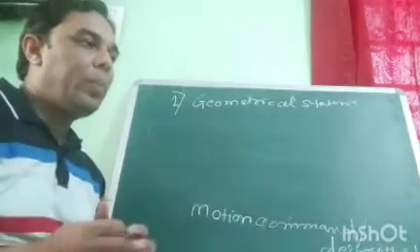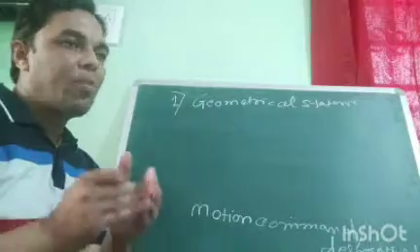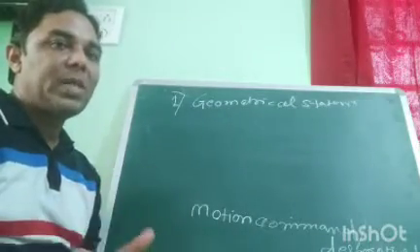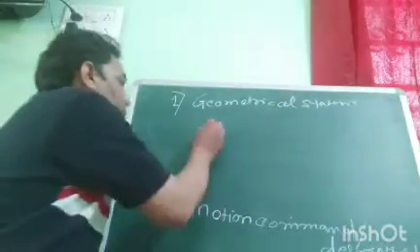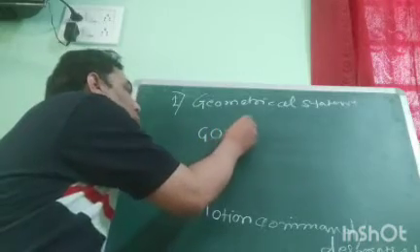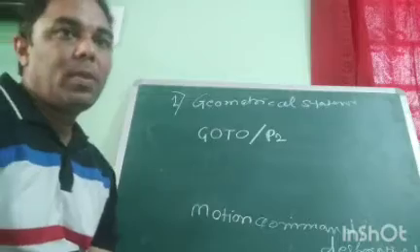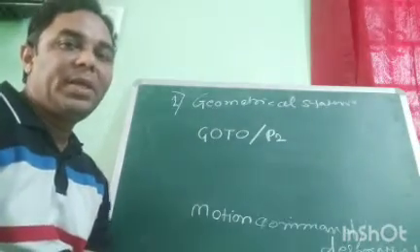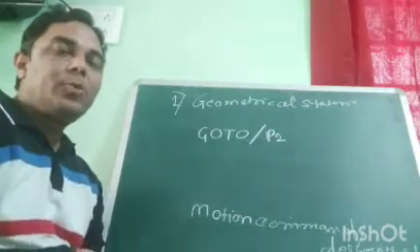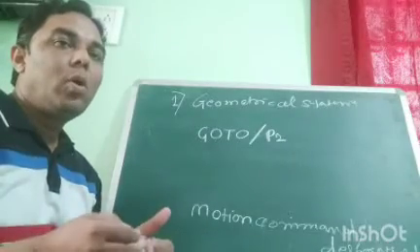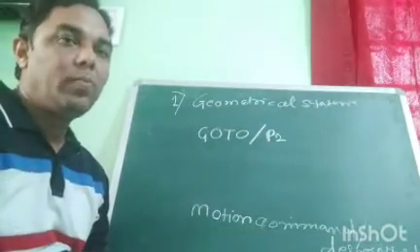So let's see how to write the motion statements in an APT part program. If I want to place the spindle on point P2, we just write GO/P2. The interpretation of that coding is that the spindle needs to go to point P2.